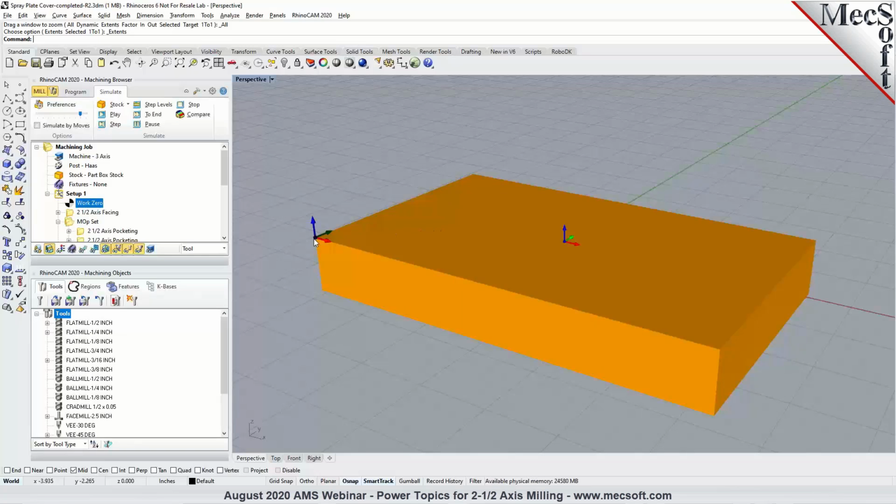So in that case, you're aligning your coordinate axes, or the coordinate axis origin, so everything will come out correctly when you machine. And the second thing that I was explaining is that in some cases you don't need to do that. You set up your work offset and have a G54 come out, and wherever that zero is defined on your machine tool, that's where it's going to start machining. So I hope that makes sense.